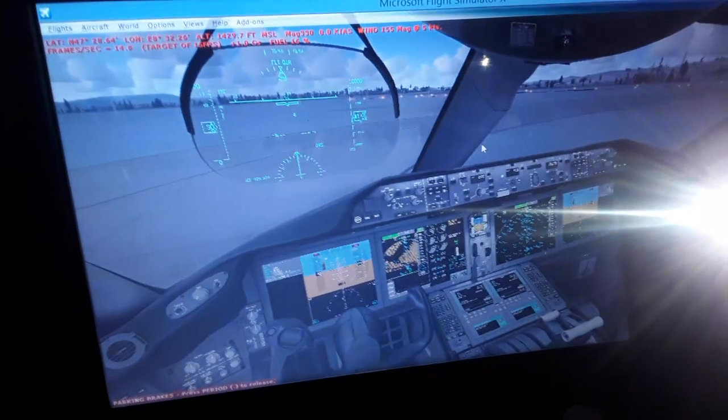We have other aircraft that fly around our own aircraft. Using the transponder, the transmitter receiver transmits our frequency to other aircraft, and the traffic controller receives from other aircraft and displays using the radio frequency. You can calculate the other aircraft's distance from our aircraft, altitude difference from our aircraft, and whether they climb or descend with respect to our aircraft. You can also calculate the closing velocity between our aircraft and the other aircraft. It will give us a warning if we have an incoming collision with another aircraft in the air. The TCAS system, traffic collision avoidance system.